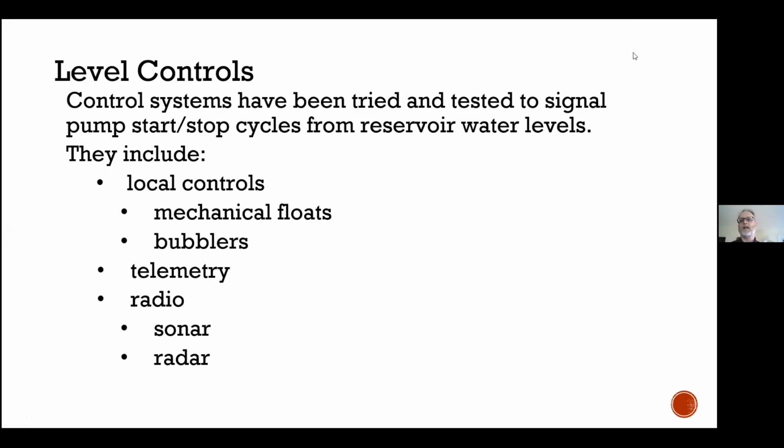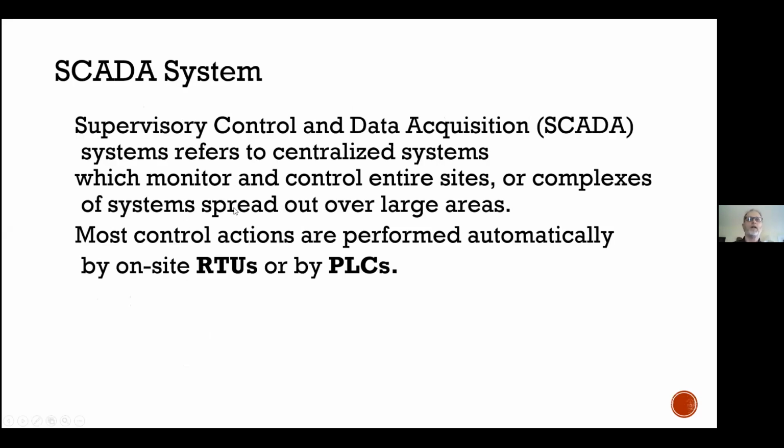And you know, in the old days, sometimes SCADA systems were just simply called alarm systems because that's basically what they did. They sent out an alarm when something was out of cycle, whether it was a pump failing to start, or a motor overload, or a water reservoir level too low, or say a backup generator doesn't turn on when it's supposed to. You may be asked what the actual abbreviation stands for: supervisory control and data acquisition.